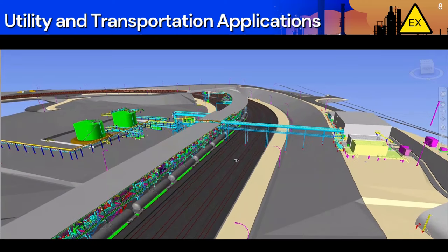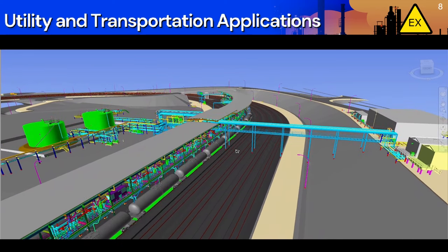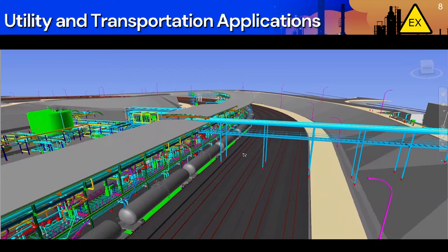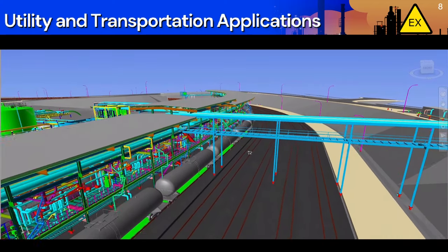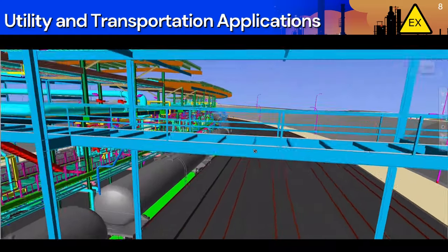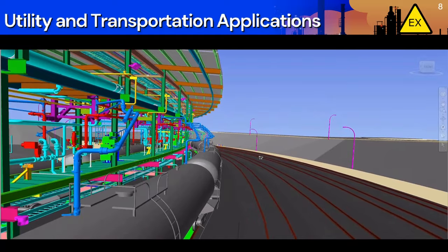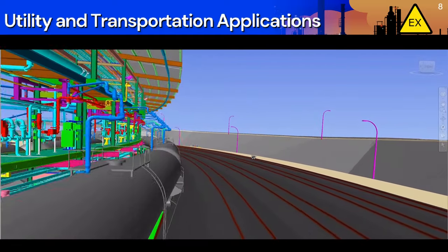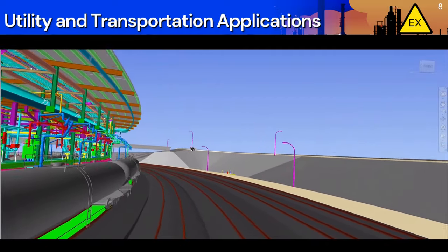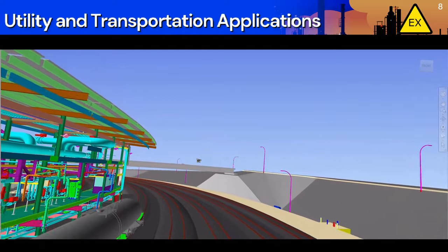Another industry sector of the economy where large quantities of flammable materials are handled are pipeline, utility, and fuel transportation applications. Many of these facilities handle natural gas at very high pressures or as liquids that have unique release characteristics. A liquefied natural gas release will expand to 500 times the liquid volume as it approaches ambient temperatures. A very small leak can create a very large hazard.